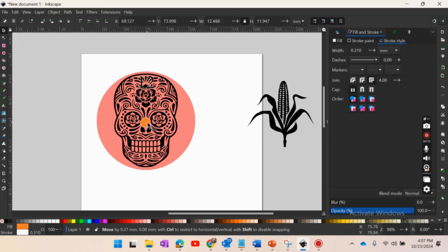So from here, what we're going to do is I'm going to get this kind of centered, but most importantly, I'm going to first be in millimeters. So make sure you're not in inches, be in millimeters. And we're going to turn off this lock setting, and we're going to type in 8 and 8 because I measured this for you already. You don't have to do any additional math, so that we can make sure that our clock components actually pop through for us.